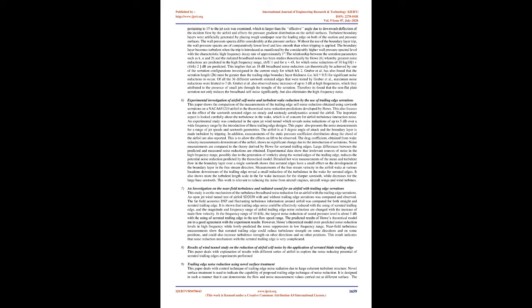plate type trailing edge serration with woven wire mesh screen is employed for the reduction of the narrowband vortex shedding noise. The experiment setup is a wind tunnel, which can achieve turbulence intensity as low as 0.1% and Mach number as high as 0.3, while maintaining a low background noise. The airfoil under investigation here was held by side plates and attached to the nozzle lips.